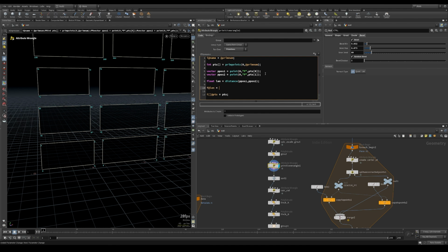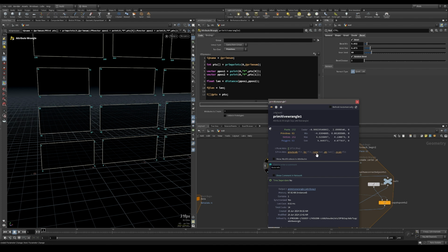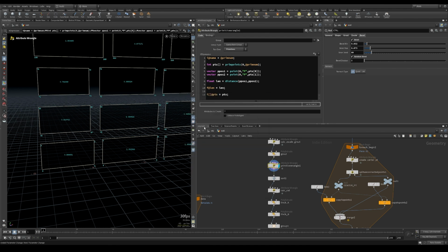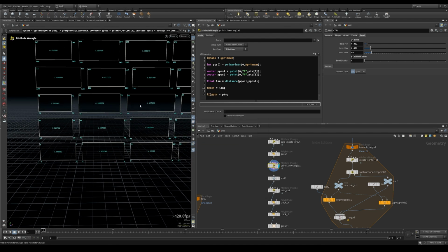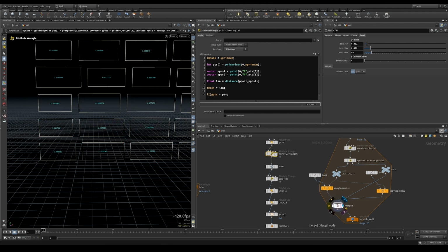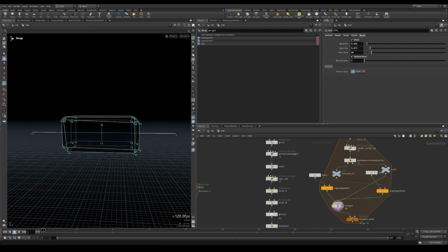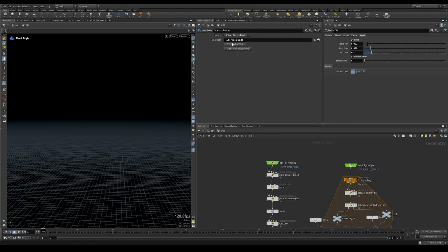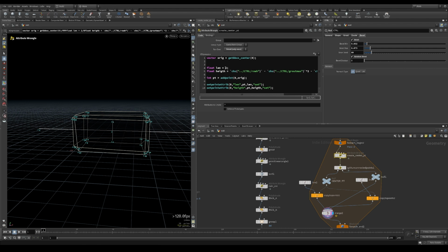Let's visualize it with an attribute, and let's try to create the visualizer for it, which needs to be a marker. And as you can see, we have the length of each brick. So now if we go back on the brick remeshing, this is already taking the len, it is passing. Let's reset the cache. And here we need to take the len variable from the primitive attribute we created. So we use the prim function, geometry 0. We want to take the len attribute from the index 0.